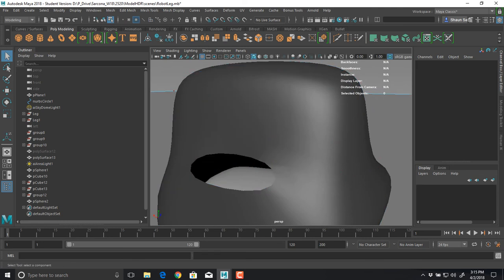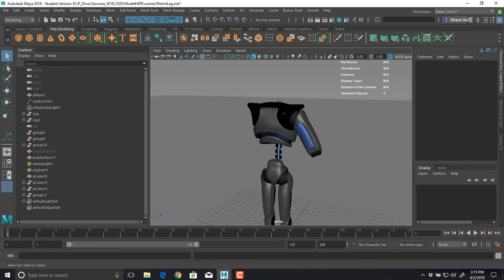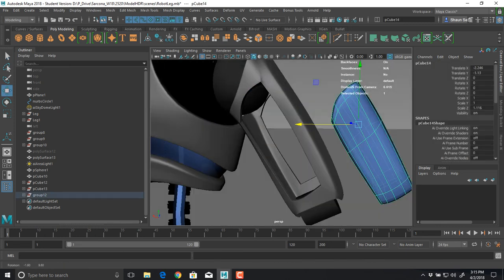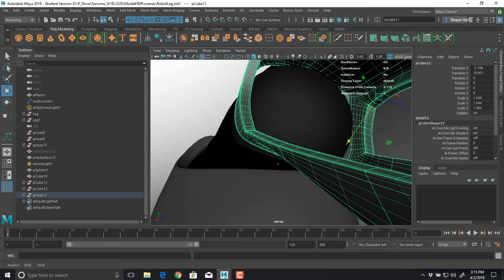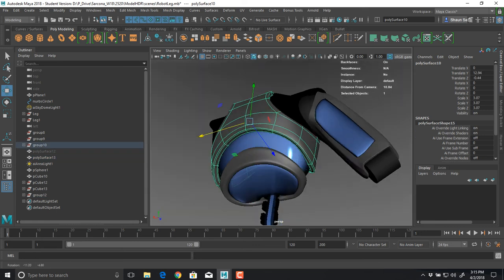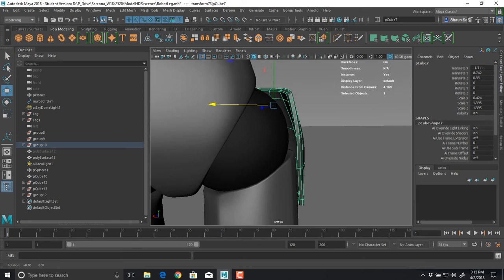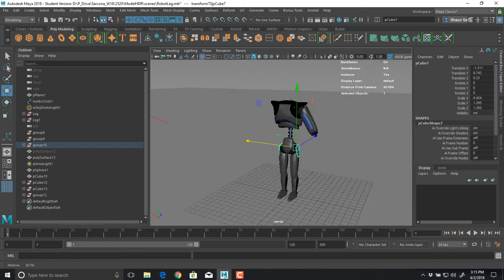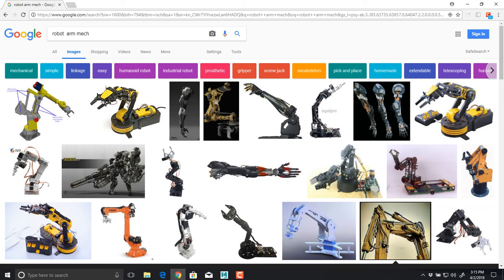Make sure your surfaces have some sort of thickness to them so they look realistic. No surfaces in the real world are paper thin with the exception of obviously paper. So even these guys here, I've extruded them so that they do have a thickness right there. And the same thing here, these have thicknesses. All of my surfaces have some sort of thickness to them. Cool. All right, any questions on that stuff yet?